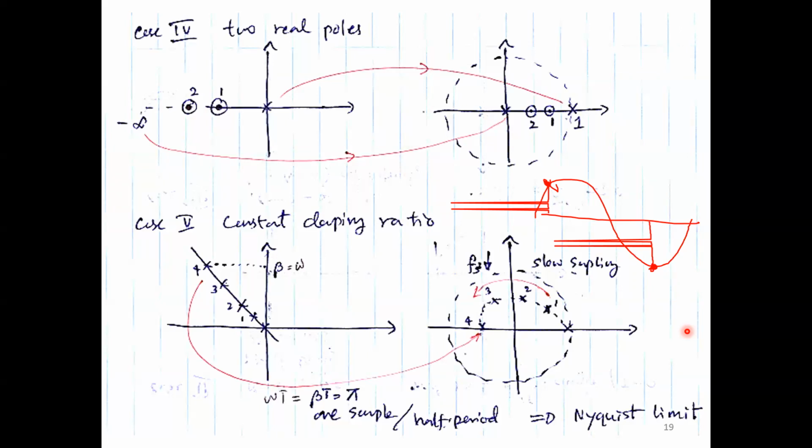And there's no point of reducing the sampling rate and increasing the angle between samples to a level where the samples you are taking do not represent the original waveforms. In that case, you don't have any advantage at all. In fact, you will actually degrade the performance of the plant seriously. Is that clear to everybody?